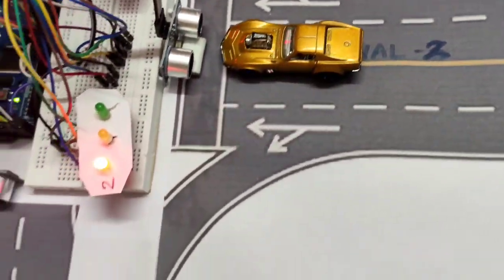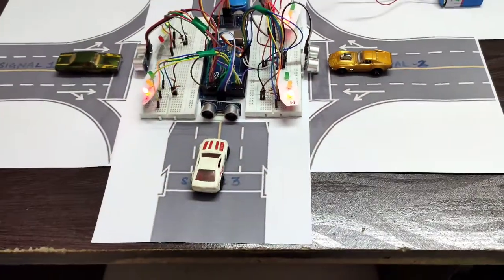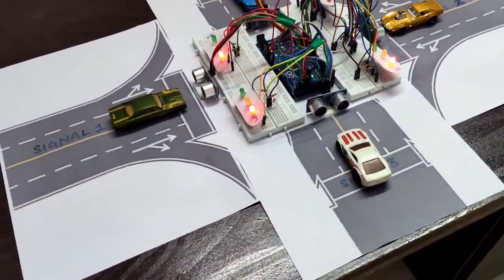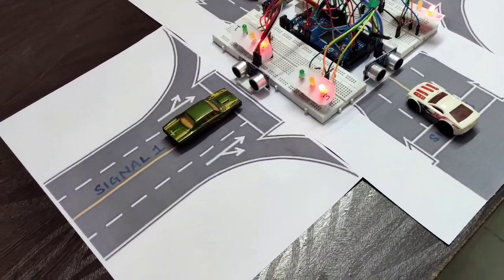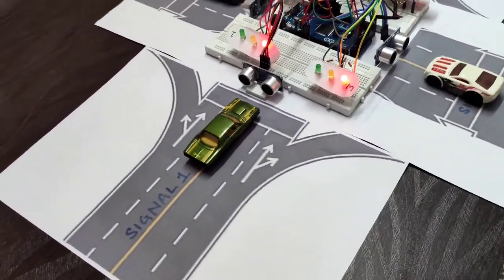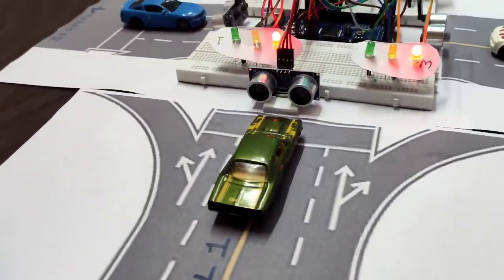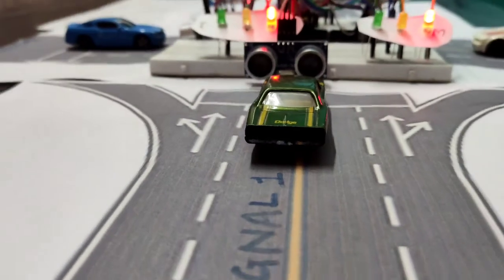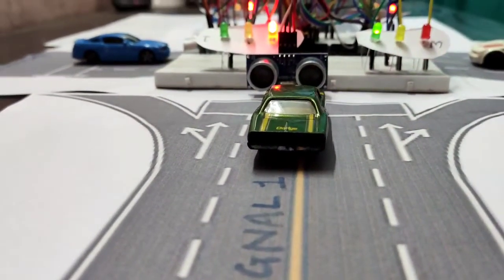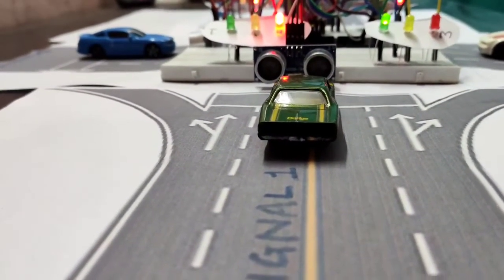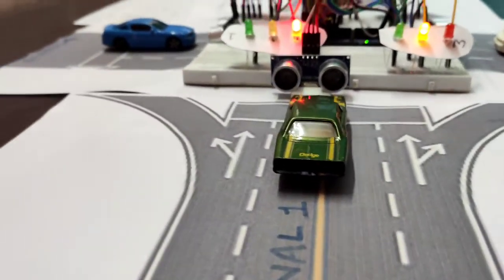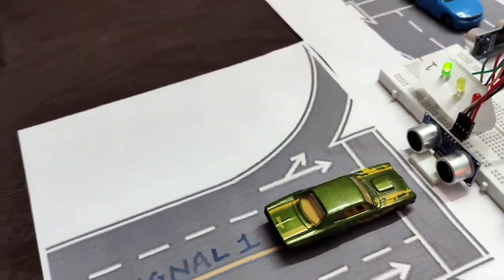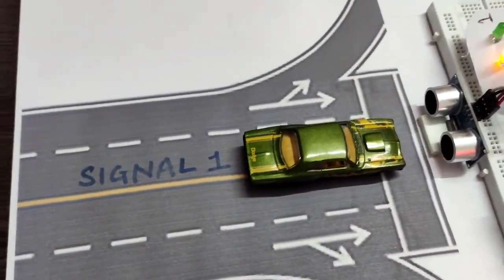This is our working project. We have used 4 sets of sensors and LEDs representing a typical traffic square, which is currently under normal working conditions. That is, it is working with each signal having a delay of 5 seconds for red light and 2 seconds for yellow light. The green signal light or green LED would be on till one signal's timing completes. Now, when a vehicle or an object is brought near the signal, the lane would be allowed to stay on until its density decreases or the delay ends, whichever comes first.